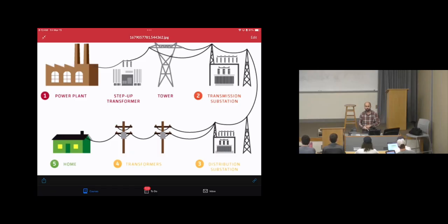Then it goes to, for example, Brown Hall, Student Center. So there is an electrical room for each building. In that electrical room, you will see another device, which is a small transformer, that converts the voltages from 7.2 kilovolts to 120, 240, or 480, depending on each building. So here in Brown Hall, there are 3 types of voltages: 480 basically for 3-phase, 240 for 2-phase, 120 for single-phase. Then it will go to the wall outlets.